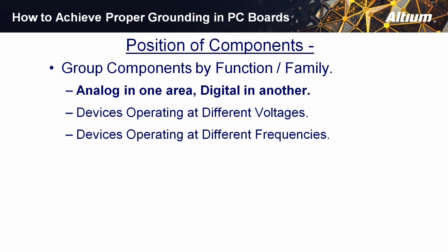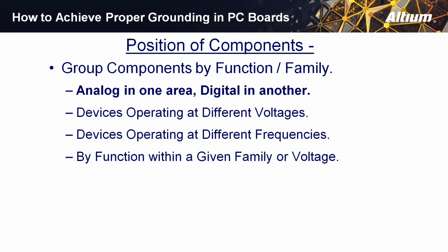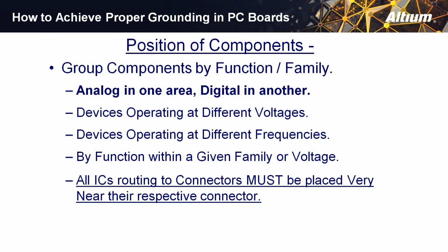Put devices that operate at different frequencies in different areas. So the high frequency analog in one area, the low frequency analog in another, and so on and so on. Put stuff together by function and by family or by voltage within a family. In other words, the processor with its memory and all of its associated devices and so on. I'm sure everybody's aware of that.